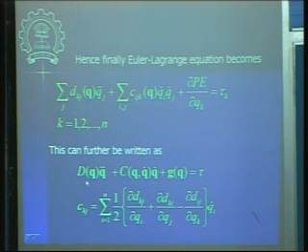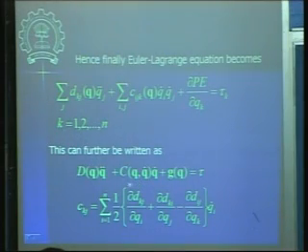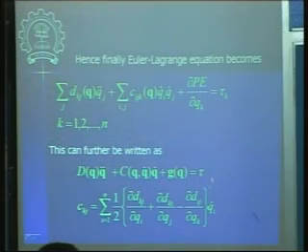These D terms are basically inertia terms, and this is an inertia because of the translational acceleration q double dot. Then your centrifugal acceleration terms and Coriolis terms are combined in this term C, the term C(q, q dot). And then your gravity vector is in this G term. That will be equal to your external forces. Now these external forces can be torque applied by the motor, or it can be damping torque also.